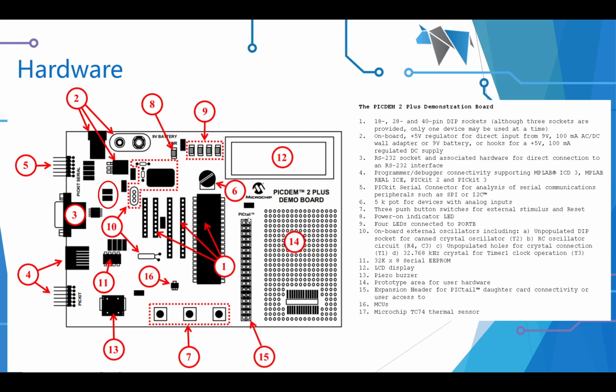This is the hardware I'm going to be using. There is nothing specific on here that is for the SPI solution because we're going to be using hardware SPI. You can use software, it's up to you. But what I'm going to show you shortly is a photograph of how I've got it attached. Essentially, I'm hooking into a couple of connections here, 3 other connections down here, and a ground and 5 volts. So I'm using the pigtail for my connectivity. Really quite easy.